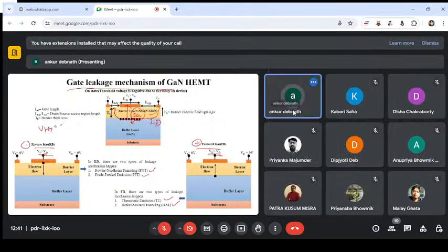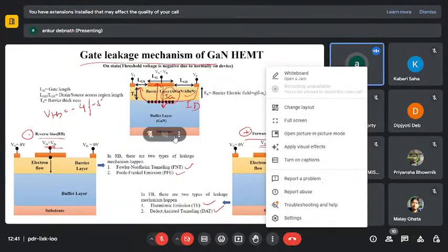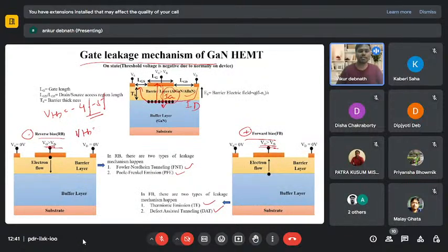A typical value could be around -4 or -5 volts. In a MOSFET, VTH is near 0.5 or 1, always positive. In gallium nitride, it's negative. That's why it's a reverse bias.